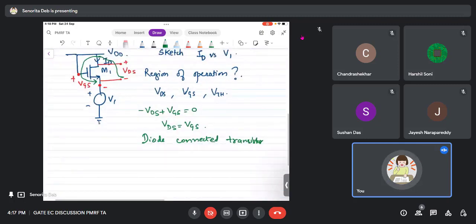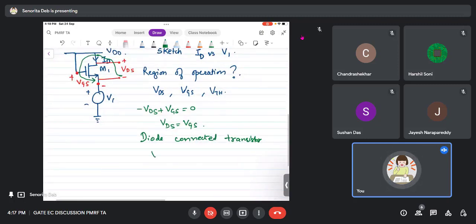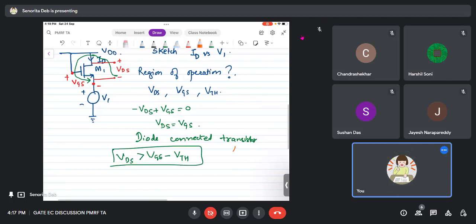Okay. In this case, VDS is VGS, and if VDS is VGS, then obviously VGS minus VTH will always be less than VDS, right? So this is always going to be satisfied. It always satisfies. So please keep on making notes as well.